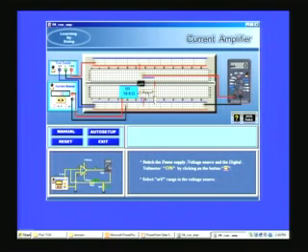You can also see here, this is 10K which is coming from pin 6 to pin 2. There is a feedback loop, right? Pin number 6 is the output, pin number 2 is the inverting input. So you put a negative feedback connecting these two through the 10K resistor, and you have the other resistor here, the 1K resistor. So the gain will have to be 11. Now I switch on the dual power supply and the multimeter, so I can start giving the inputs.